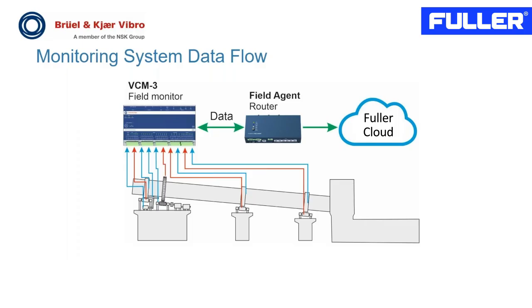It has 12 dynamic signals that are sampled with 200 kilohertz, DC coupled synchronously. Synchronously very important for this application. We have tacho signals to measure speeds. We have digital inputs. We have additional network inputs to connect to local control systems. So we get additional information like power of the motor and temperatures and similar.